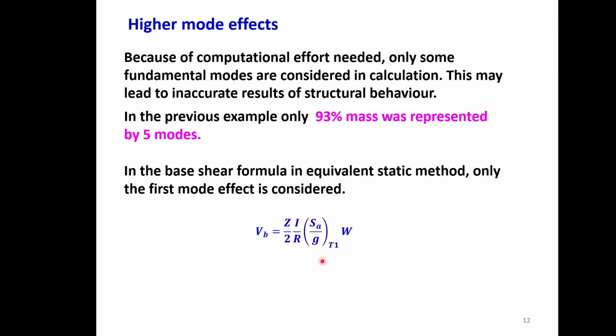So you see obviously here in the computation of the base shear you are considering only the first mode. Though you are taking all the masses, the seismic weights, together, the vibration effect, the dynamic effect, you are taking only for the first mode. So this will lead to some inaccuracy and higher mode effects will be left out.